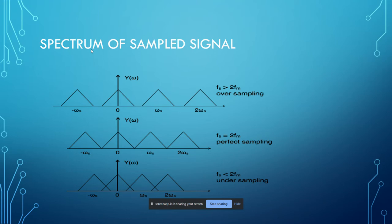After that, we see some of the spectrums for different sampling frequencies. First, the top one is the oversampled signal. That means the sampling frequency is much greater than two times the maximum frequency. That will not affect the signal recovery at the time of reconstruction. It will not affect anything, and no higher frequency is going to be added to the original signal. The second one is the perfectly sampled signal, the Nyquist sampling signal.